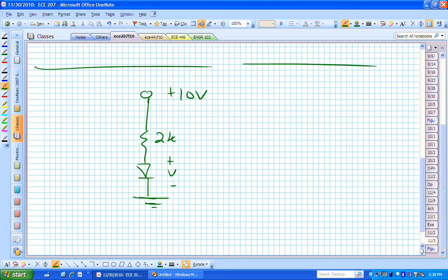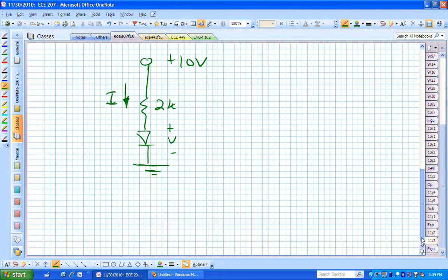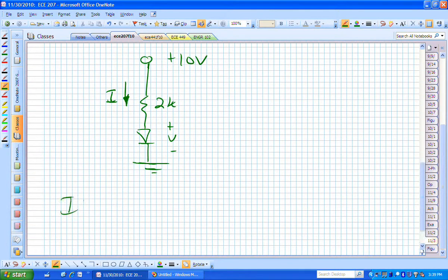For example, this circuit is going to have a current flowing through it if the voltage being applied exceeds the forward voltage V on the diode, which if we're assuming an ideal diode, we might just, to get us started, assume that that voltage is 0. And when it's conducting, it's going to be 0 volts dropped across that diode, if that was an ideal. I think that's what we talked about last time. If we had an ideal diode, and remember, this particular configuration is equivalent